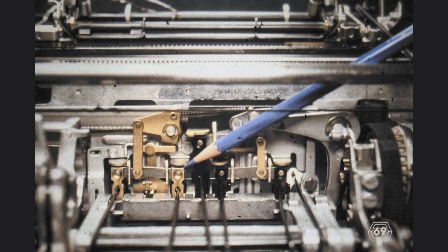At this point, you should depress the character T and then hand cycle the machine while observing the indicated tilt 1 latch. Try to observe the amounts of motion that occur here. You should, for instance, notice that the vertical input motion of the selector latch, provided by the action of the cam follower or the latch bail, is a whole lot greater than the output motion of the link, which connects the latch lever to the tilt bell crank. It turns out that the tilt bell crank experiences only 1/3 of the motion obtained by the tilt 1 latch.